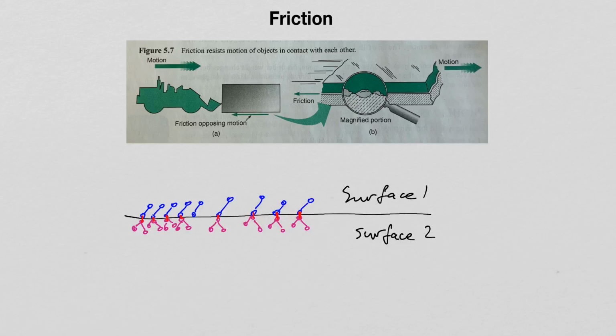Now, depending on whether you have more surface irregularities or smoother surfaces, one of the two mechanisms responsible for friction will dominate. For surfaces that are rough, we have more of a mechanical interaction than bonding of molecules. For surfaces that are very smooth, we have more of an adhesive force action rather than mechanical interaction.